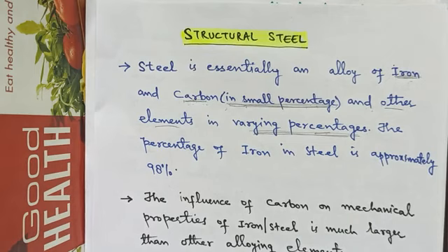Now, as per IS 2062-2011, that is, Code of Practice for medium and high tensile structural steel, there are 9 grades of structural steel with a new grade designation system based on minimum yield stress. Table 1 of IS 2062-2011 gives the chemical composition of each grade.